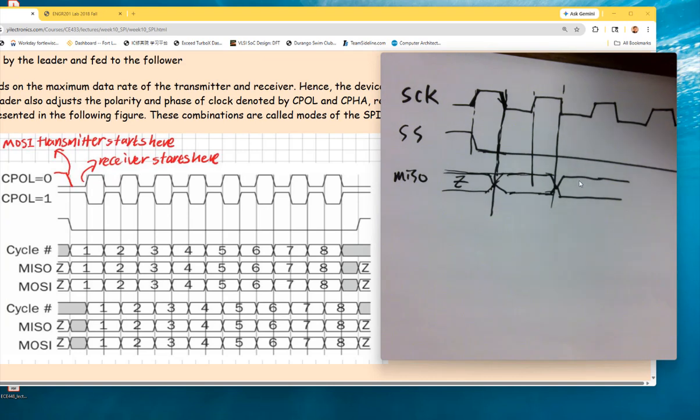Right? So SCK is a rising edge. So you are here, I didn't draw it, but there should be a rising edge. The rising edge pulls this down, okay? And the falling edge starts the data. So start from here. It's basically a clock polarity of 1, and also the phase is 1. So it's a 1-1 mode for this operation.